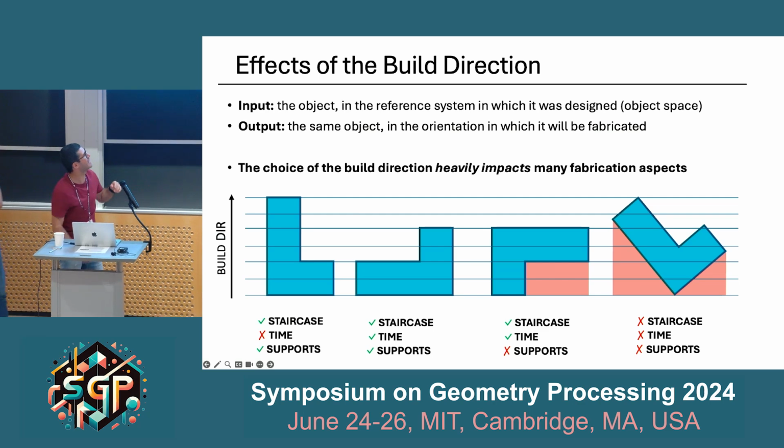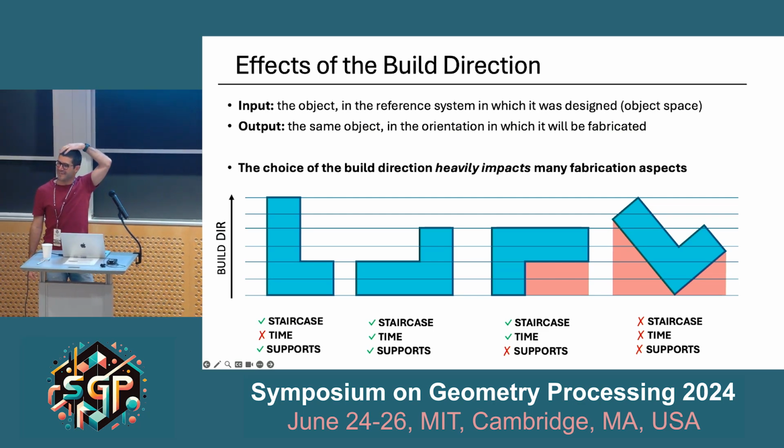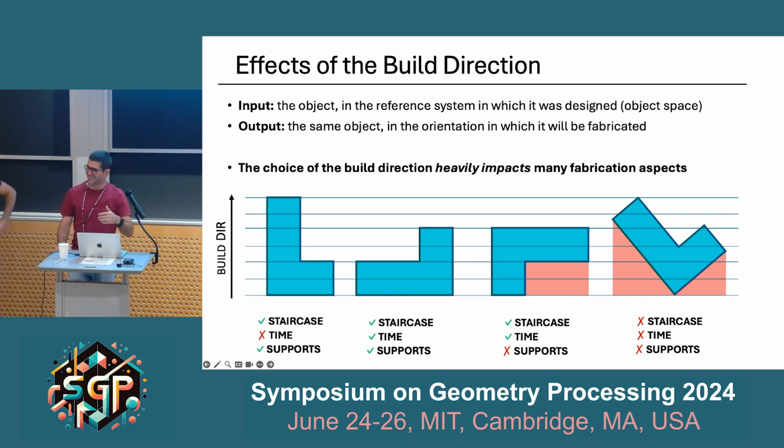Like if you were a guy printing on metal, you go for that solution. I cannot really give an exhaustive explanation for this, but talking with people who operate metal machines, what they told me is that essentially they look at the slices one on top of the other, and they try to make sure that the subsequent slice is sitting as much as possible on top of the previous one, because in terms of the effect of the cooling down, this is the best thing that they found heuristically.